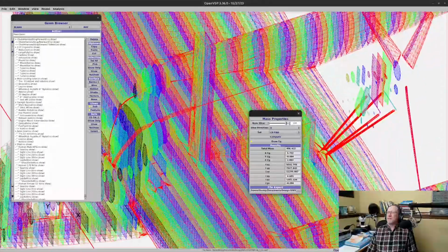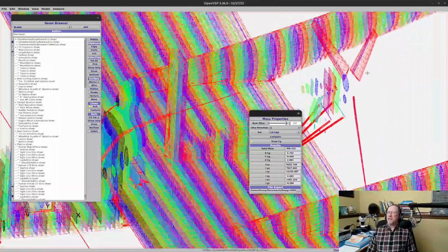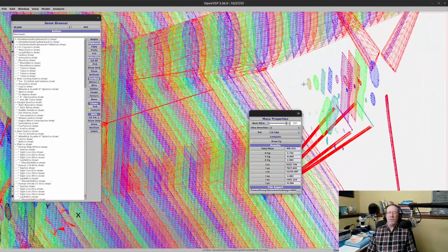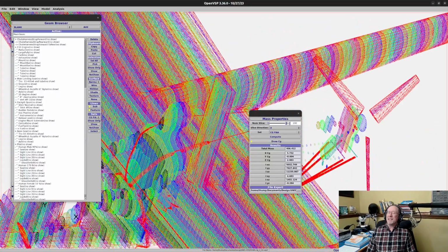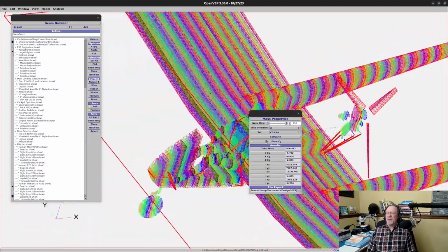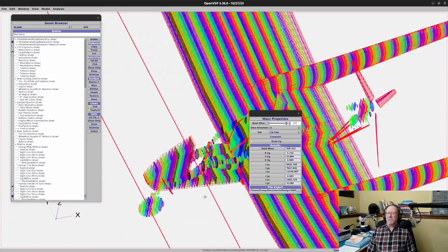Okay, we got our slices. By the way, you can see how the slices are a little bit coarse, even though we have almost 200 slices. This is the carburetor and the engine and the redrive. So it's not going to give you perfect numbers on weight and on CG analysis, but it'll get you in the ballpark. For example, it has a very slim slice here on the propeller. But that's okay. We're just getting close.